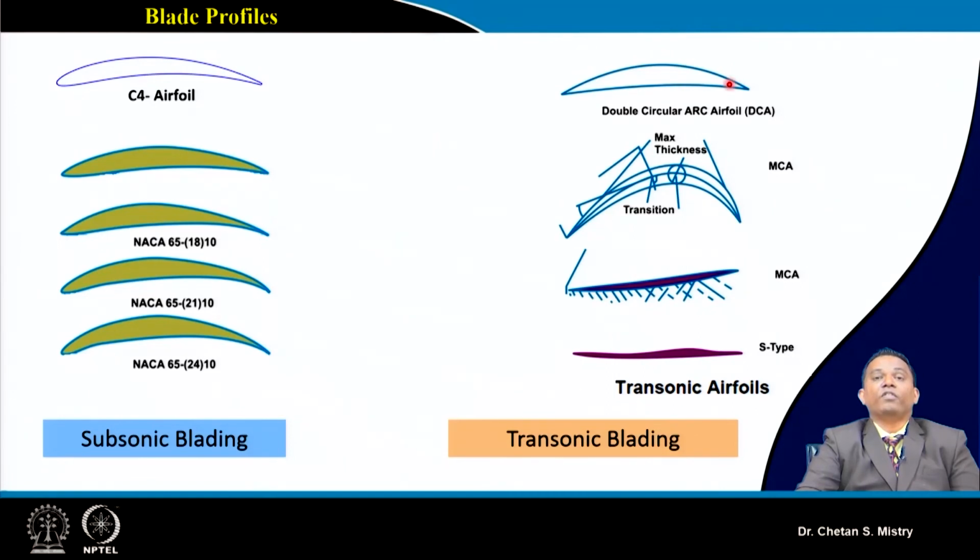In the same way, we will have slight turning or rounding near the trailing edge. Now this flow passage that we are making as a suction surface needs to help us in managing the flow within the flow passage. So the radius we select is very important for our double circular arc aerofoil.